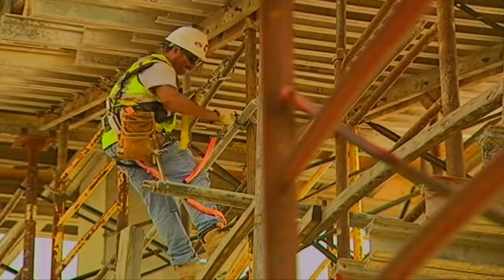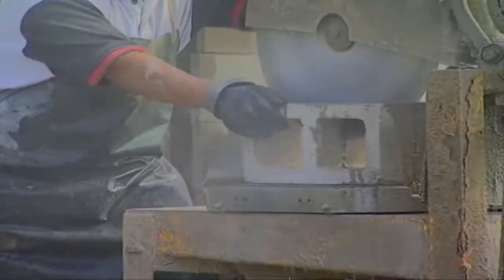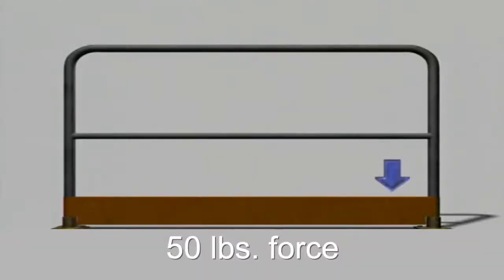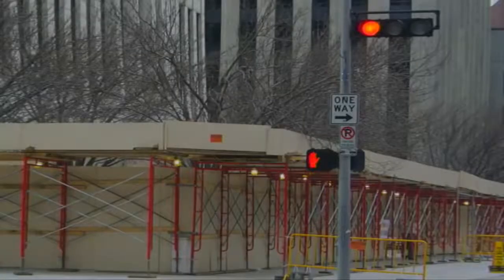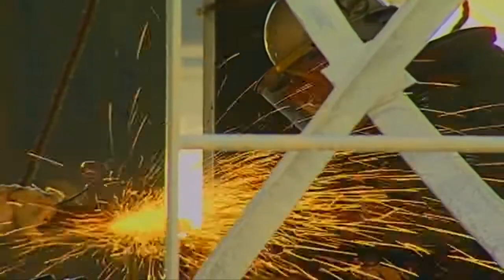Workers working below the scaffold must also be protected by barricading the area to keep them out of danger, and canopy structures must be used when objects could fall from the scaffold that are too heavy to be stopped by other protective means. Install toe boards along the edge of platforms that are more than 10 feet above lower levels. Toe boards must be able to withstand a force of at least 50 pounds applied in any downward or horizontal direction at any point along the toe board and be at least 3 1/2 inches from the top edge to the level of the walking, working surface. The use of paneling or screening, a guardrail system, a canopy structure, debris net, or catch platform can protect workers that are working on lower levels.